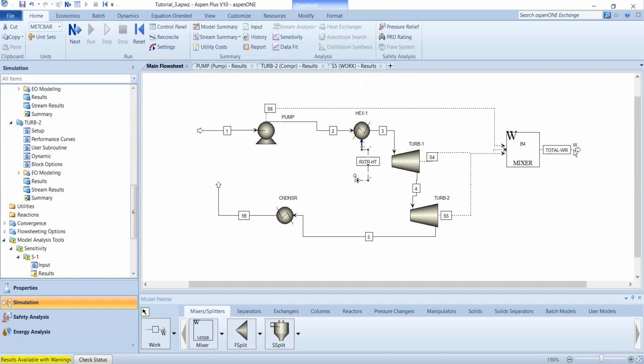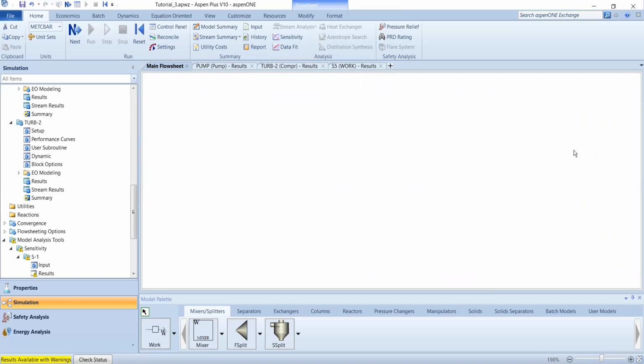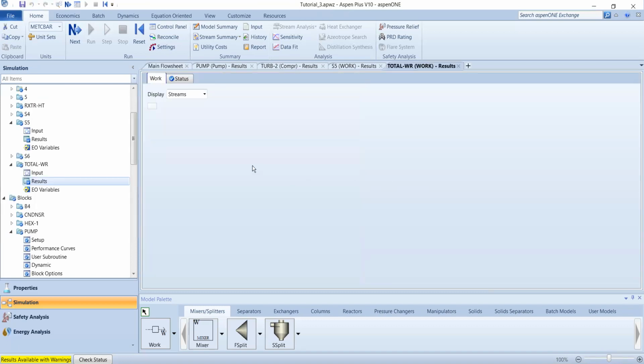The power produced is this guy, which is, how much is this? Let's have a look here. Which is 33.526 megawatts, right? So your energy efficiency is 33 divided by 200. Okay, and this is your total electrical efficiency of the power plant, right?